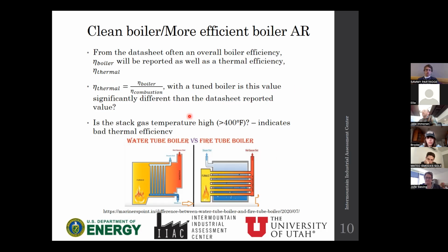And then the other indication of this is if the stack gas temperature is high, that would mean that heat isn't being effectively transferred into the water. Similarly, if the stack gas temperature is high, we could also just recommend that they get a more efficient boiler. More efficient boilers will have higher thermal efficiencies. For one that we just did for one of our assessments, the boiler they were using had a thermal efficiency of 80%, and we recommended one with like 95%.